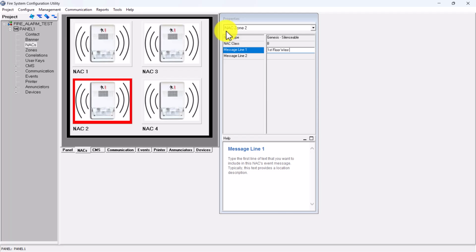Once you upload the loop into the map, from there you can make every point type available inside of the programming menu. And all you have to do is just put your message one or message two, however long the message is. Smoke detector. So smoke detector, we're gonna have one basement above FACP. And this one is gonna be first floor elevator lobby.